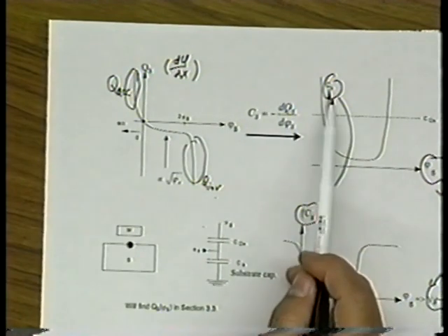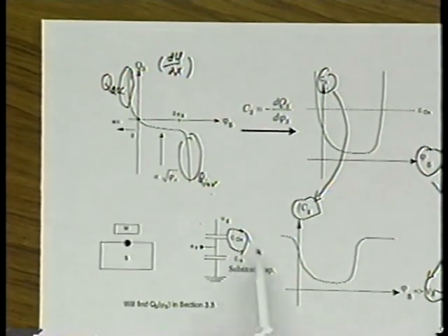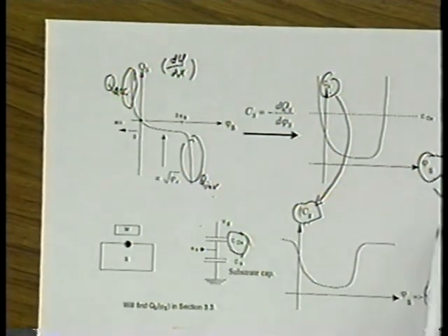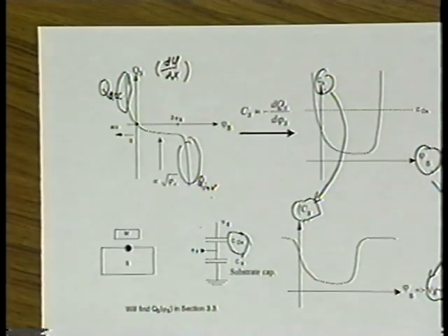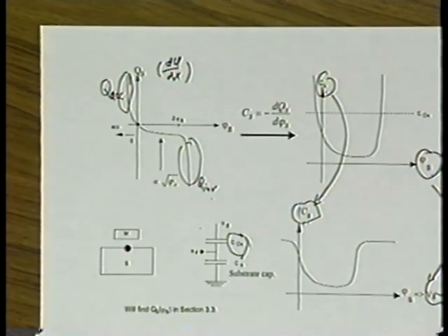We simply put the Cs in series with a constant Cox, yeah? Then we end up with a total capacitance Cg, right? This change is not so trivial, so we'll talk a little bit about that next time. All right? Any questions about what we discussed today? Okay, so we can do that, and if you like, you can also think a little bit about how you would make this change, transition between phi s to Vg. Okay?